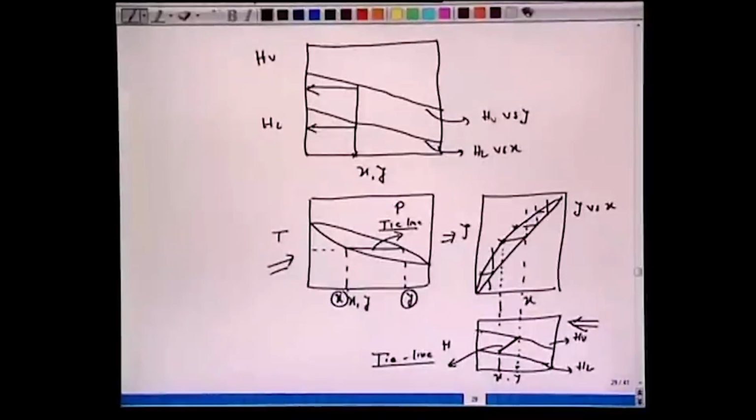And if we fix X and temperature, the enthalpy of this component is fixed here for this liquid, the saturated liquid phase. Similarly, fixing Y and this temperature, we have fixed the enthalpy here. And the two we are trying to mark on this curve, the HXY diagram. How do we do this? X, we have taken the projection here from the top, and Y we have taken the projection here, on the saturated HV curve and HL curve, and we connect them to make this the tie line.